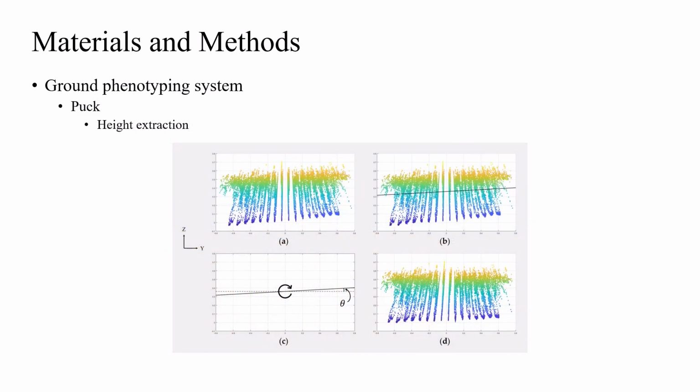The pre-processing method first fits a linear least squares curve to a point cloud's YZ plane, converts the curve slope to an angle, and rotates the point cloud in the opposite direction of the slope by the angle so that the point cloud becomes level.